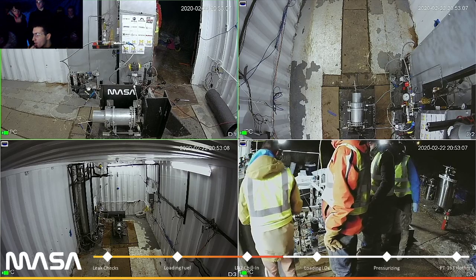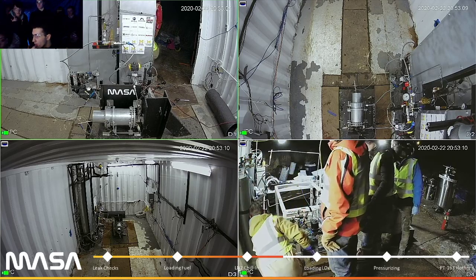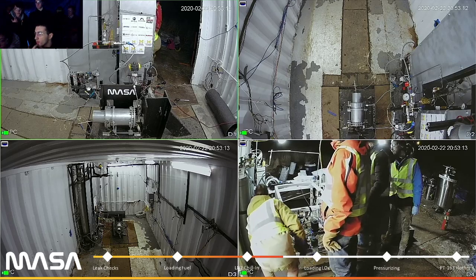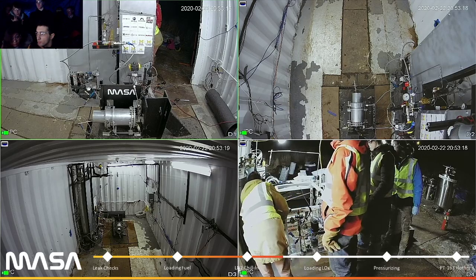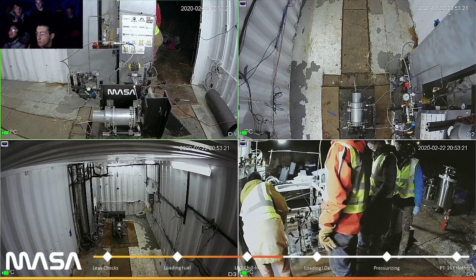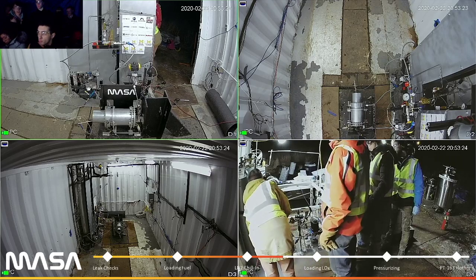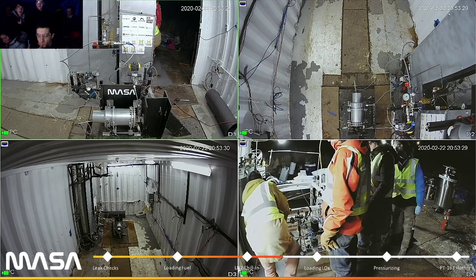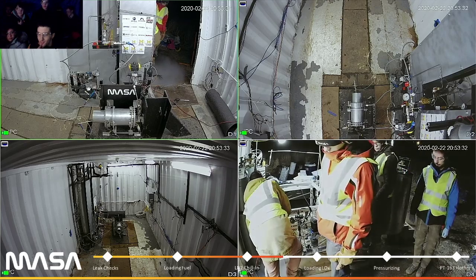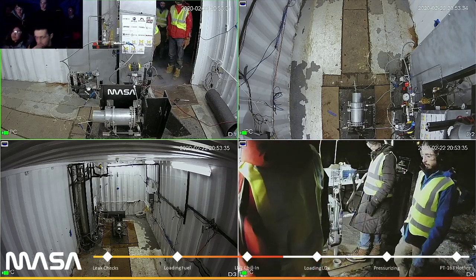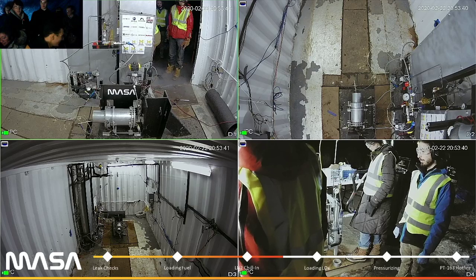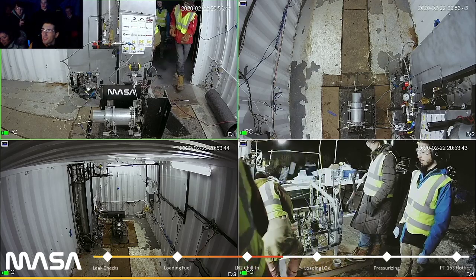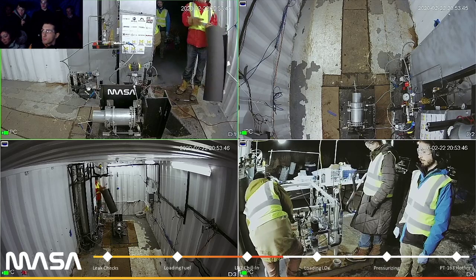Basically, our engine controller monitors the amperage draw and the voltage draw through all of our solenoids, and we also monitor the time the command is sent to open the valves. We also have pressure transducers before the valve and after the valve, in different parts of the engine circuit. So when we run a cold flow, we can see exactly, down to 10 milliseconds, when our valve was commanded open, and at what time pressures are seen at various points of the engine. Then we can use that data to link up the valve timing with the engine controller and the actual time we need to start the engine with the igniter.